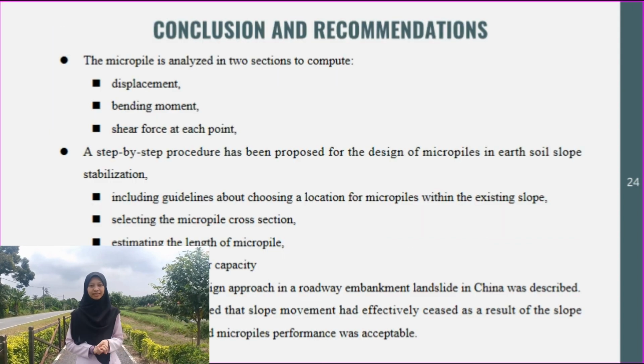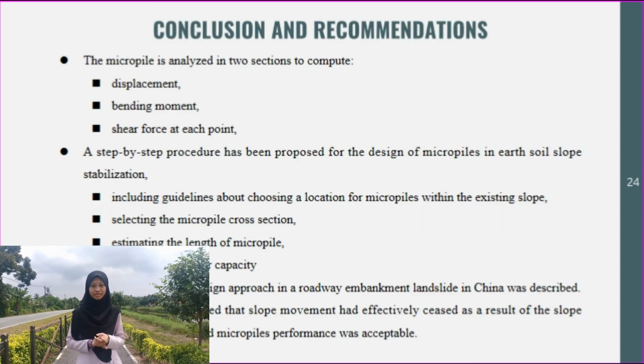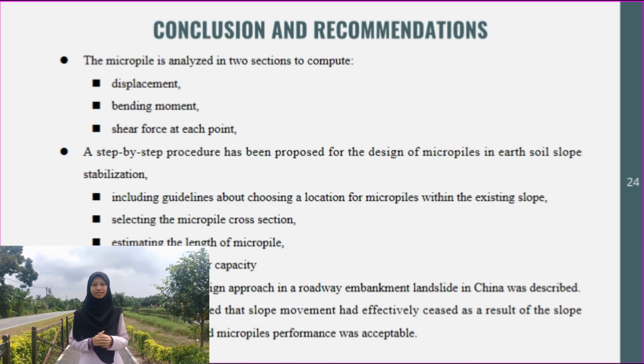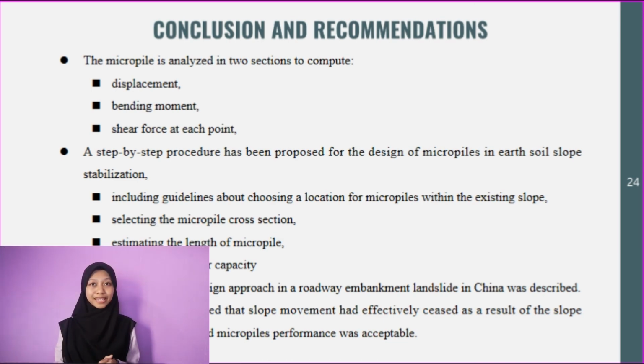In conclusion, the micropile was analyzed in two sections to compute displacement, shear force, and bending moment at each point. A step-by-step procedure has been proposed for the design of micropiles in earth slope stabilization. An application of the design approach in a roadway embankment landslide in China was described, and monitoring data indicated that the slope movement had effectively ceased as a result of the slope stabilization measure, and the micropile's performance was acceptable.